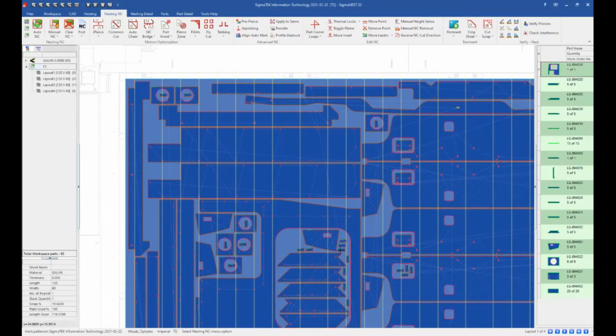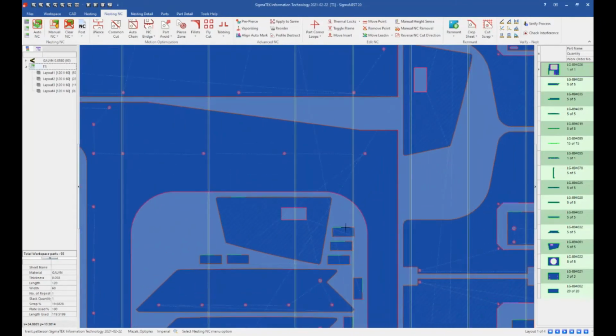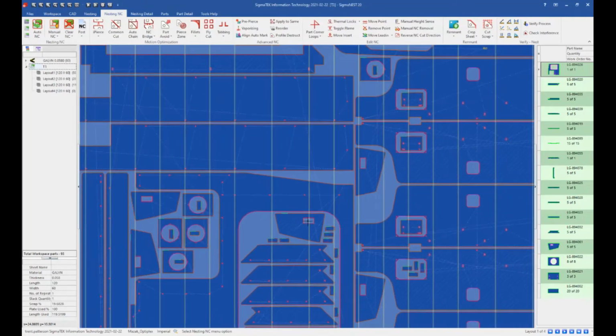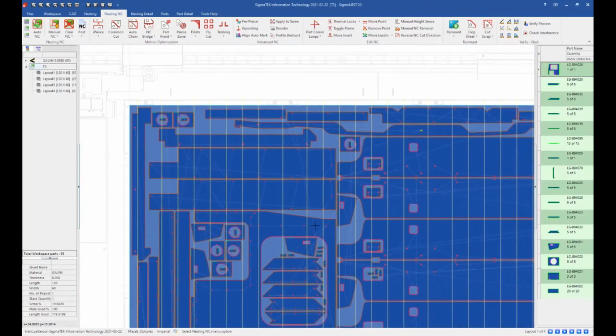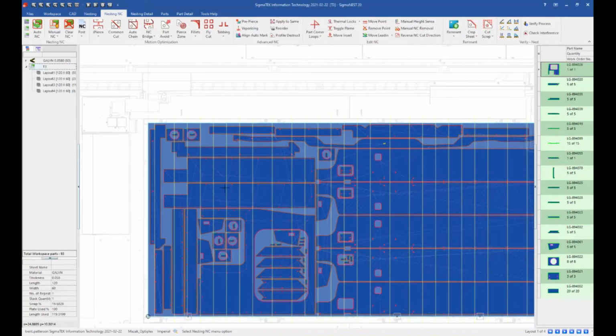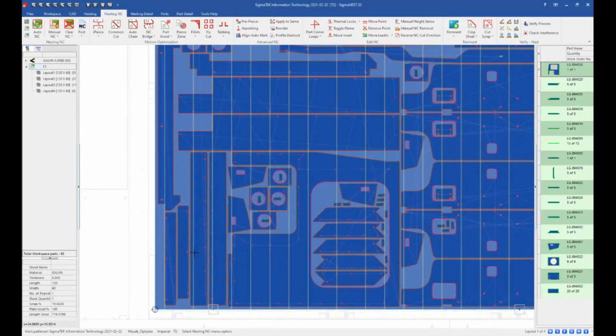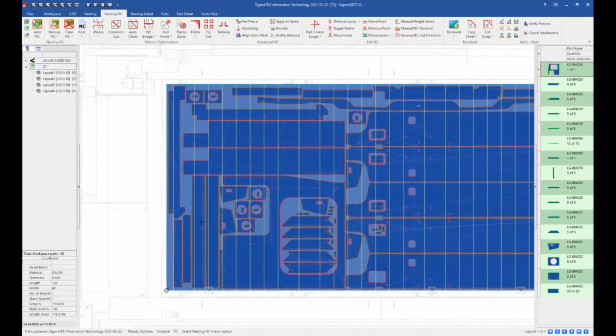We will see here that a lot of our smaller parts are going to get tabs, or parts that only fall across one slat are typically going to get your tabs, but usually anything that is on 2 or more slats is not going to receive a tab. Now this is also looking at your vertical parts too, and it's still applying the conditional tab feature. So it's saying that this is not going to be applied. So that is one thing to take into consideration. Make sure that if you're using center of gravity tabbing, that you do have your conditional tabbing parameters set up correctly as well.